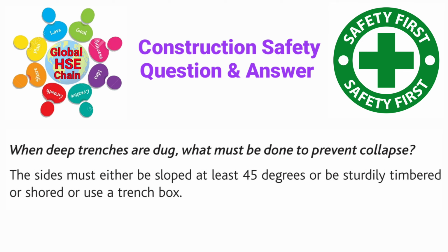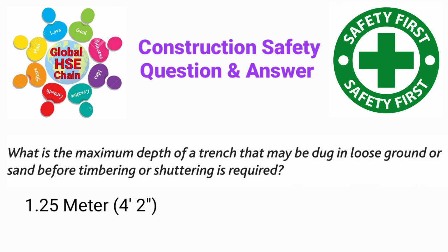Question is, what is the maximum depth of a trench that may be dug in loose ground or sand before timbering or shuttering is required? The answer is 1.25 meter or 4 feet 2 inch.